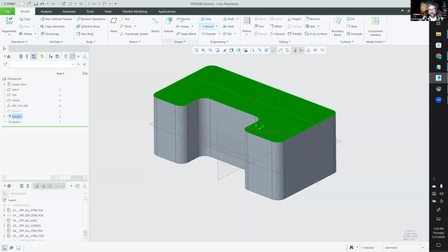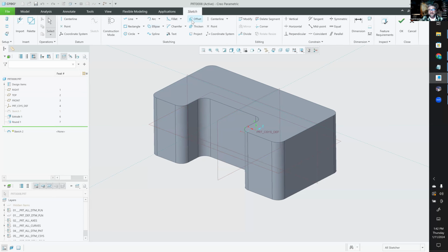I'm going to create a sketch on this wall, and I'm going to use the offset edge to offset one in. Let's do project and then offset. This is new in 9 and 10, and it's more like how we do it in surfacing. People who are really good at sketcher mode find this really irritating. So I'm going to hold the shift key down and move my mouse around. That's pretty cool, but a little different than how we typically roll.